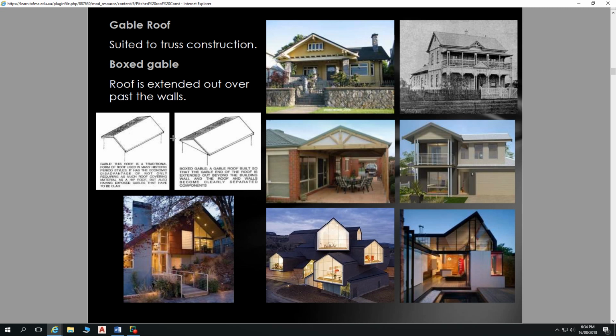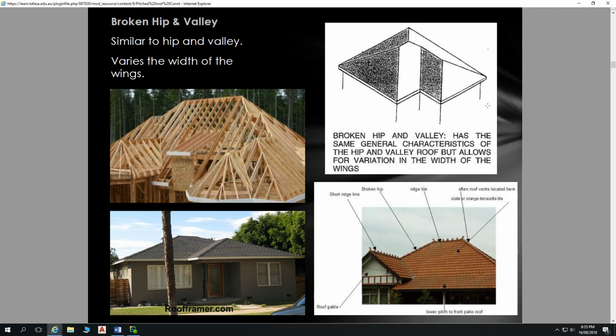Which one? Truss frame. Yes. Yeah. So with trusses, a gable end is very easy to do, but also, and traditionally, hips were the preserve of conventionally pitched framing, whereby we cut all the rafters and put everything together on site. But that's also very commonplace now to use trusses for gable ends, so for hip ends as well.